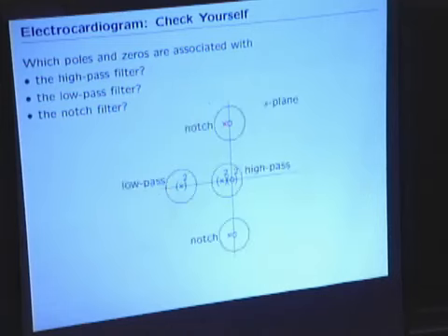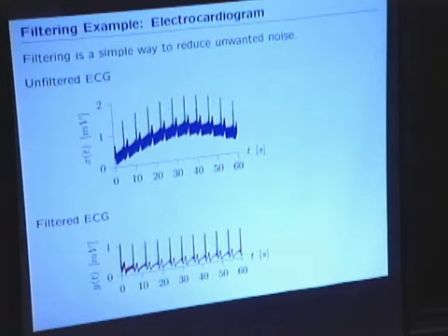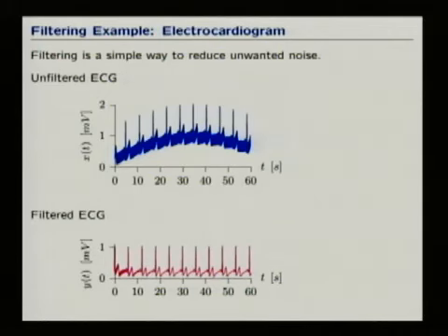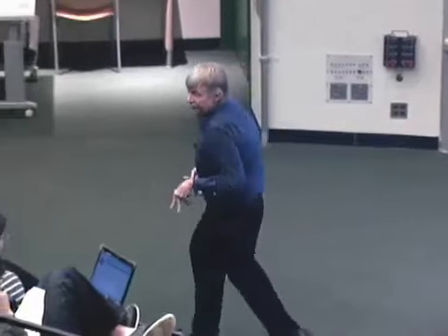Okay? And when you design such a filter, you clean up the waveform a lot, and no one in their right mind would generate an EKG machine that didn't do this, right? I mean, that's just built into the pre-amplifier that's attached to the electrodes. So the point is that filtering is a very important application of Fourier transforms. We can take an arbitrary signal and often get a lot of insight into what we would like to preserve and remove by thinking about the Fourier transform. Insights that you wouldn't get by looking at the time waveform.